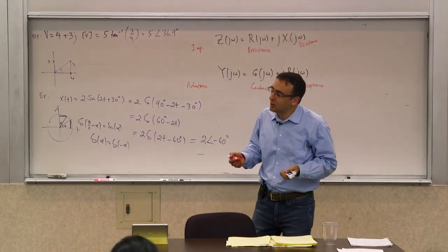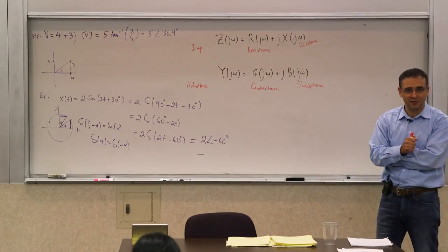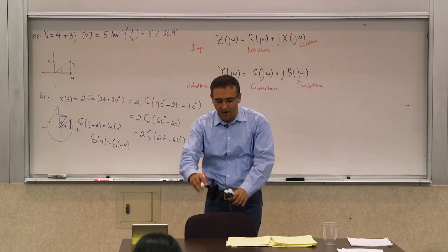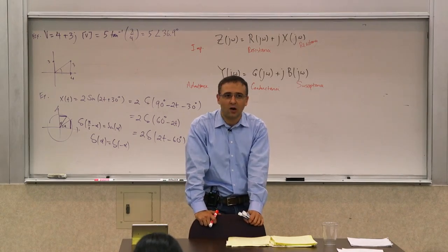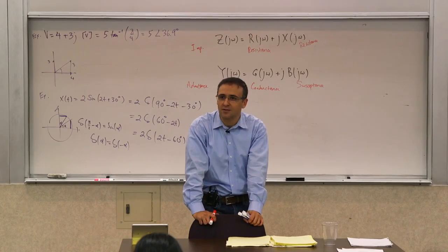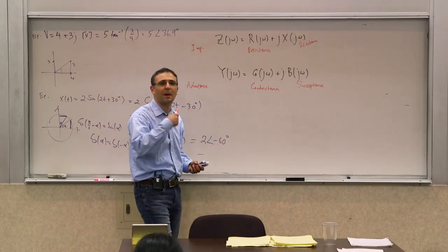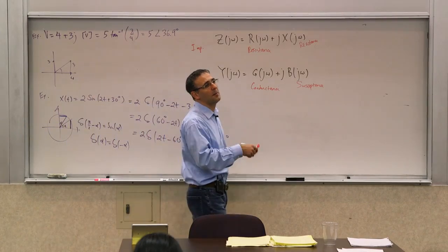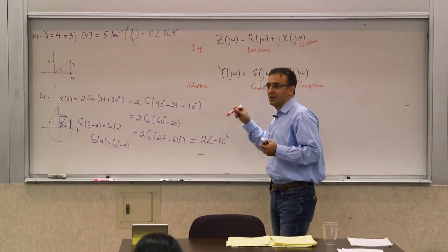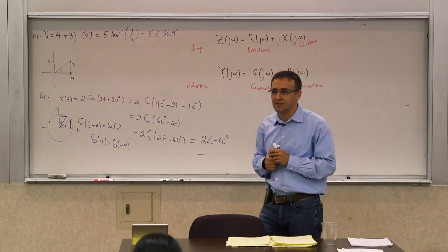Now, why is this important? Because it allows you to define an impedance if you know it's driven by a sine and a cosine constantly, to deal with it that way. Now, I said in the beginning that sine and cosine are important drives, but what kind of systems actually use sine and cosine drives? Can you think of some? Power systems, right? AC power. All the power network distribution, everything is in sines and cosines. So there are a lot of these calculations for power systems. You essentially just write the phasors and manipulate the phasors, just add them, KVL, KCL over phasors.